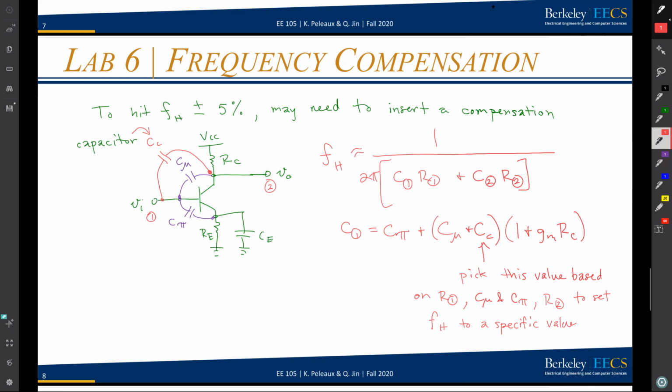And so compensation capacitors are used for a lot of different things. The dominant pole compensation we learned about in op amps is a capacitor added so that the open loop frequency response of your op amp has a pole at a low frequency. And that's done for stability purposes. This is just for your own knowledge. It's not something you're going to be tested on. But when you have an op amp, you want the feedback to stay negative. Otherwise, you might get instability and get oscillation.